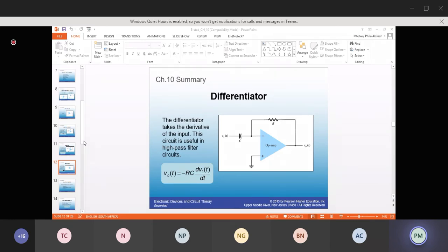You must be able to measure that 220 volts. You must be able to measure the output of a transformer, and obviously the output signals as well: your +5, your -5, your +12, your -12. It could also be nice to see, between -5 and +5, what voltage do I measure there? What is the maximum possible DC voltage that can be produced by this versatile project of mine?